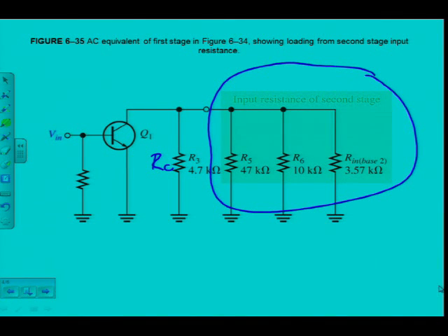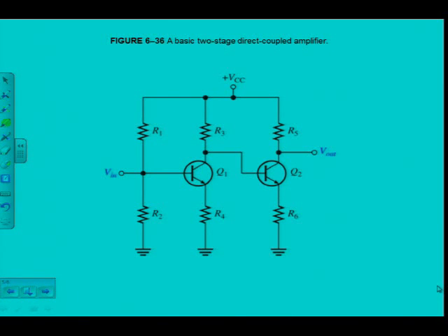Alright, the last thing here is, remember this amplifier that we've discussed was a capacitor coupled amplifier. Now you also get the multi-stage amplifier, which is direct coupled multi-stage amplifier. A direct means there's no capacitor between the two stages. And now can you see what makes it different? Here's my first stage of amplifier. Up to there's my first stage. Can you see? There's my voltage divider. There's my input. Output is taken at the collector.